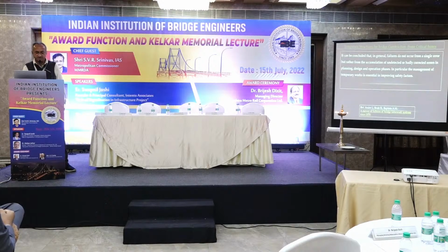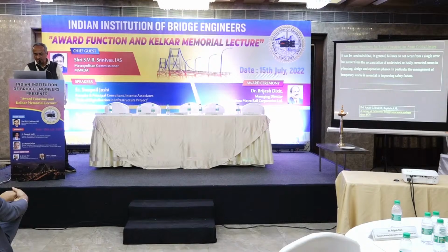So in conclusion, it can be said that failures do not occur from a single error, but rather from accumulation of undetected or badly corrected errors in planning, design, and operation phases. In particular, management of temporary works is essential for improving the safety factors.